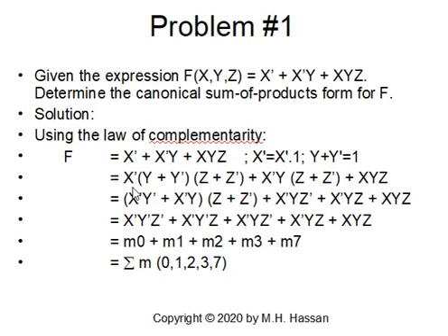So by doing this, we can say x prime and y or y prime and z or z prime is related to x prime. So we expand it here, and then we multiply to generate all minterms. The same thing with x prime y. Expand, we multiply it by z or z prime, which is also 1, plus x y z, which needs no expansion. So x prime y multiplied by z or z prime gives x prime y z prime, x prime y z, plus x y z.